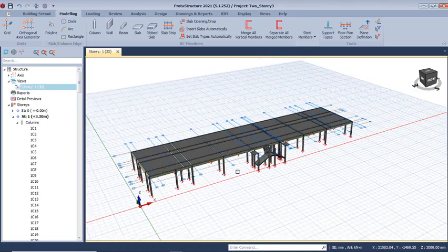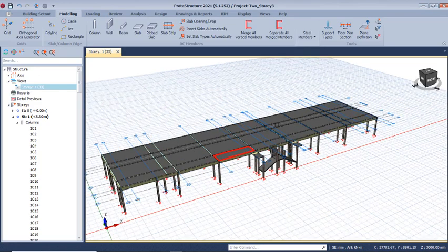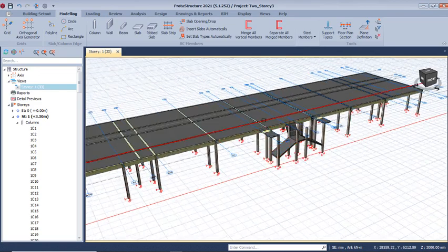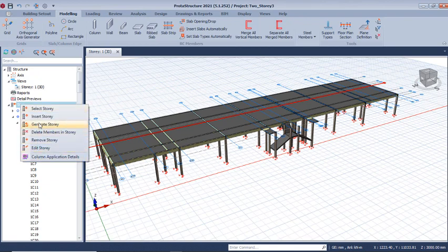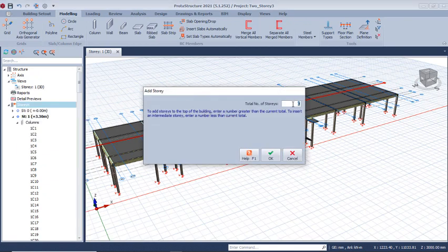Before then, we'll be setting story. This is just a two-story building. So let's generate the stories. After inserting story, select this, right click, and then come to the insert story option right there. Since we are considering a two-story building, we are going to have 3 plus the roof 3. So we click in 3 right there. Click on the OK option and the yes option.